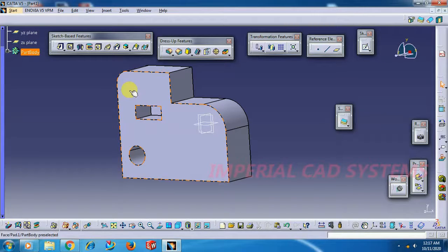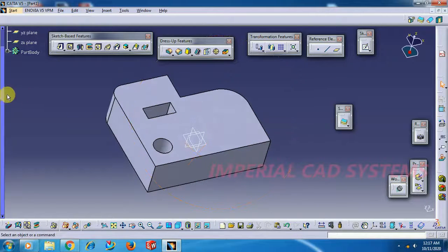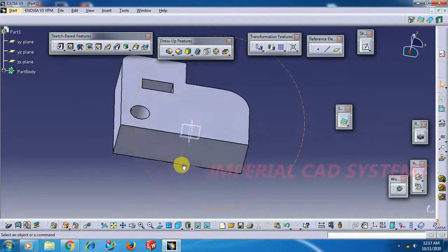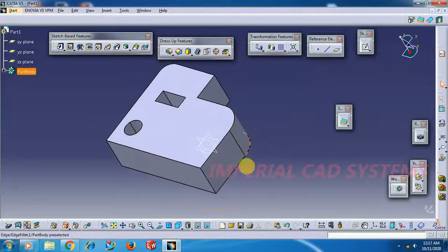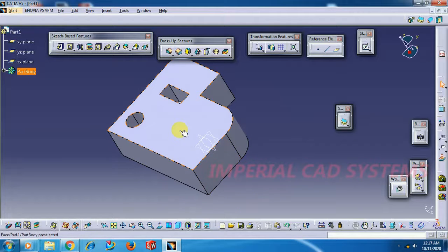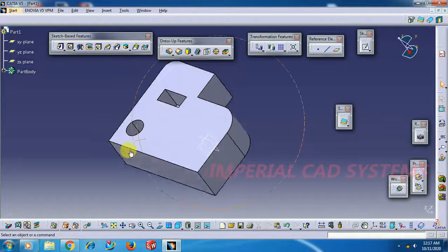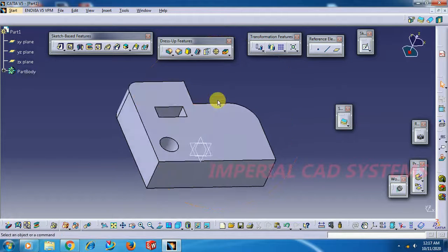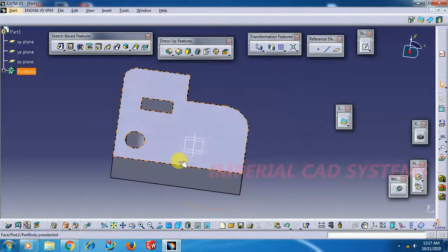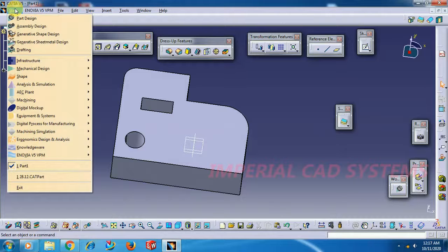So to generate a 3D model, we need to go into sketch, 2D, create a 2D profile, exit and add material. After that, if you want to generate an output of this part, that means to send this drawing to the production, what we require is front view, top view, side view, section view, dimensions on a paper printout. So for that, you can't show front view, top view, side view, all these things in this workbench. Then the third workbench we need to go for drafting.